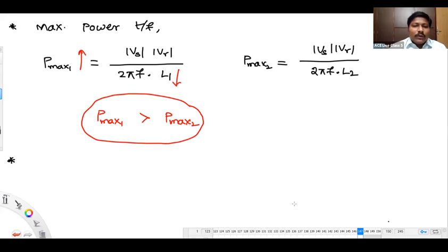Which system will have more corona? Corona depends upon two things. One is the radius of the conductors. Next one is the GMD. GMD is also one of the factors which will decide the corona. Already in the previous class, in the discussion of the bundle conductors, we said that to have low electric field intensity, GMD must be high. If the GMD value is high, electric field intensity is low, corona will be less. If you want to check back, see the equation we discussed earlier.